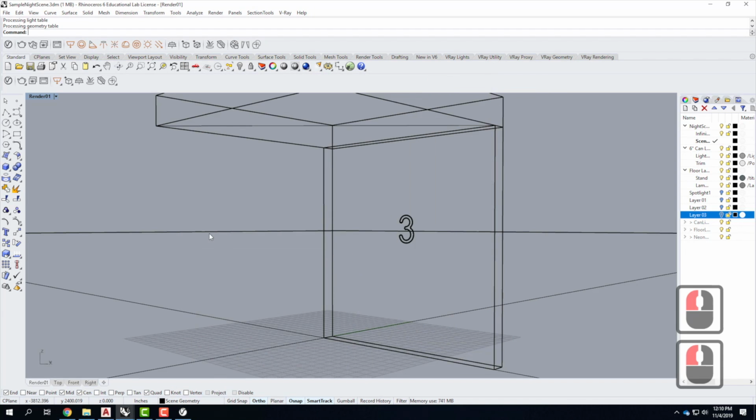I told you today we're going to concentrate on point lights and spotlights. The truth is that a rectangular light is a better light for this choice because we can put the rectangular light right behind where our neon is and then have it shine. That's what I'm going to do. The problem with a rectangular light is it's not as scripted in terms of values. So I can tell you to create a spotlight or a point light, set up the watts, and then it's going to show up like a 60-watt bulb or a 100-watt bulb or whatever.